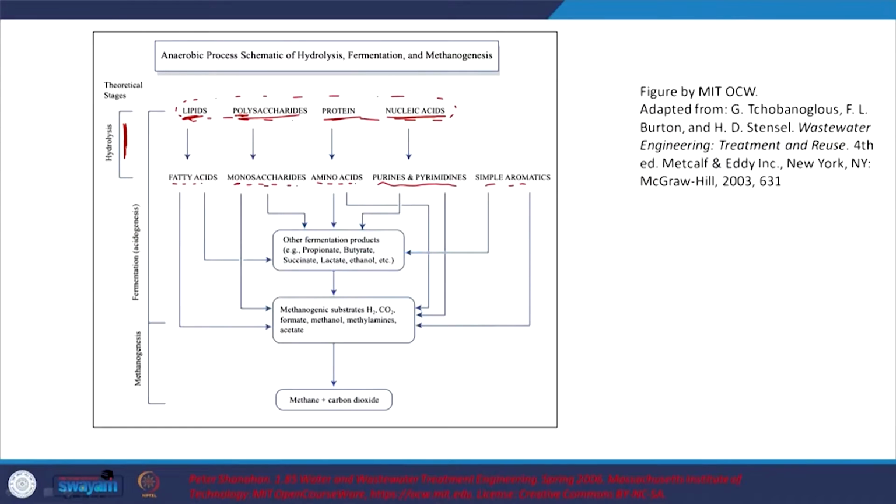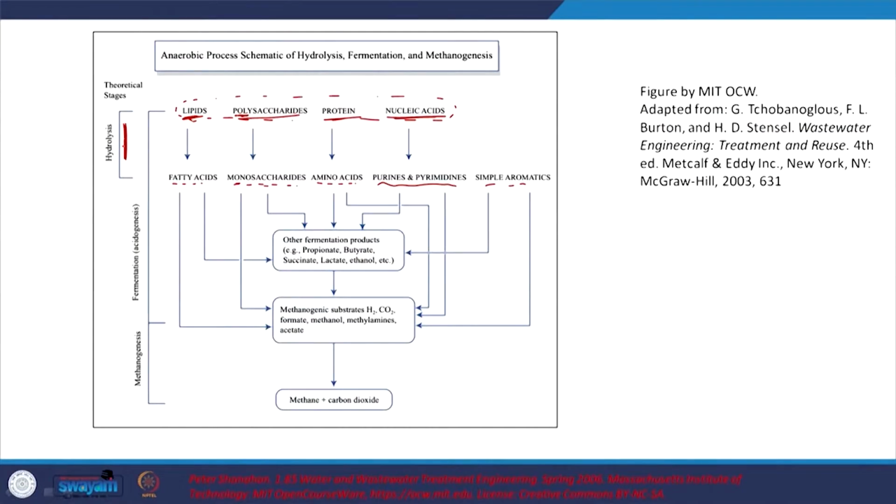I am just talking about another aspect which is relevant here, at least in the Indian context. So, that organic waste too I can let undergo anaerobic digestion and get energy from it, but the hydrolysis will be pretty slow because of the type of waste. So, typically people grind it with water or the sludge and create a slurry, right. So, hydrolysis is one aspect and that can be typically slow depending upon the type of compounds that you have at your inlet.